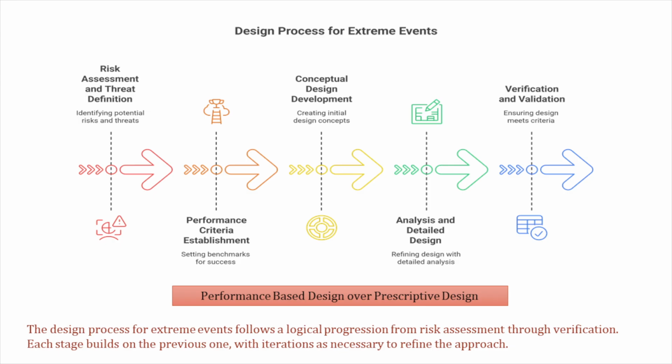Let us say for our conventional design, we will have a performance level where my structure is always in the serviceability limit. So what we used to do is that for all the structure, no matter what its usage is, we always used to define the same serviceability limit for all types of structure. So what used to happen was some structures came to be over designed. So now we are looking into a performance based design, where depending upon the usage of the structure, depending upon the requirement, depending upon the importance of the structure, we define different types of performance level and associate it with each type of structure.